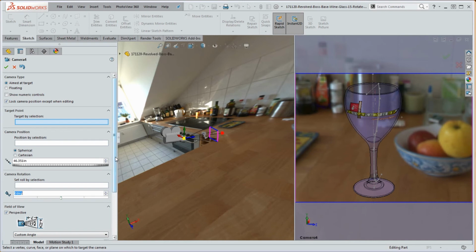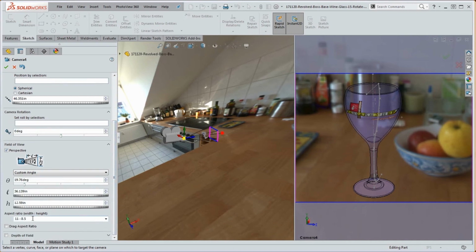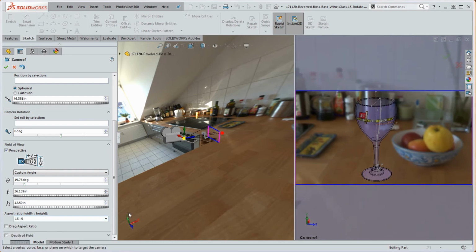But one last thing you want to do down here is you want to get the proper aspect ratio before we actually finish this. Probably should have done that first. But what we want to do is we want to get the 16:9 HD TV format. So it's not the 4K TV, but this one is HD. But that's that format that we want. We want about 800 by 450.